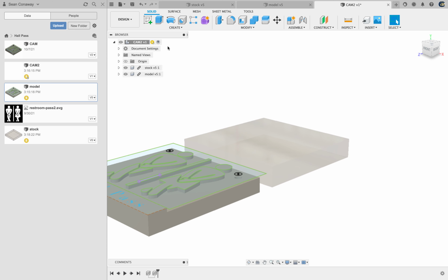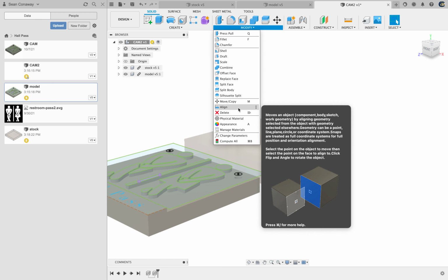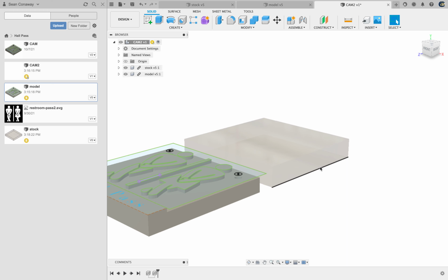So I use a tool that I here called adjust, right? Sorry, I'm having a bit of a brain moment, guys. Align, sorry, yeah, it's align right there. I'm going to use this align tool basically to stick edges together, okay?